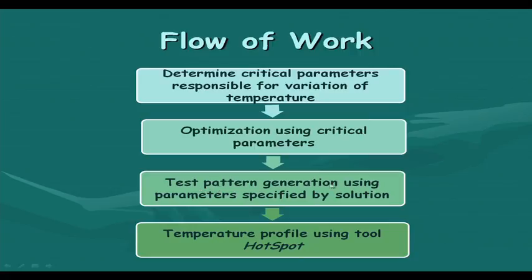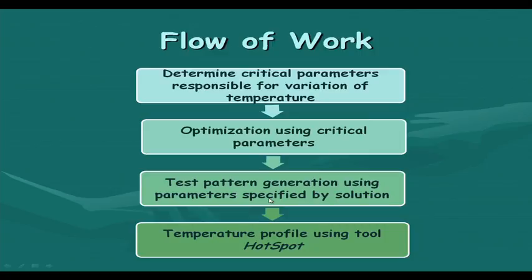Then this test pattern generation will be done using the parameters specified by the solution. So, this solution will tell us what are the typical critical settings for the LFSR, and based on that we can do these things. Now, once we have done this test pattern generation, we can do a thermal simulation using, say, the tool HotSpot or a similar thermal simulation tool to get the temperature profile of the resulting situation.